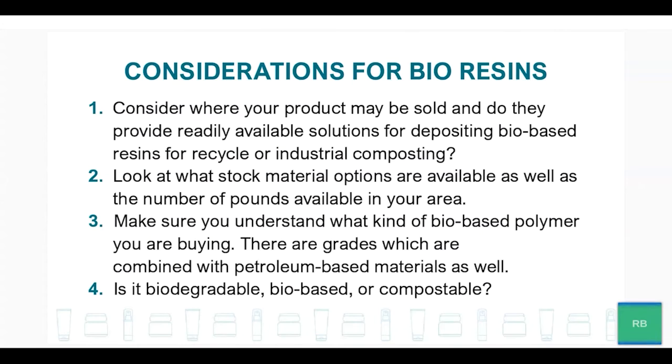Bioresins. Consider where your product may be sold, and do the local governments provide readily available solutions for depositing bio-based resins for recycle or industrial composting? Look at what stock material options are available, as well as the number of actual pounds of material available. Many bioresin manufacturers don't have a larger, broad portfolio of materials with ranging properties.